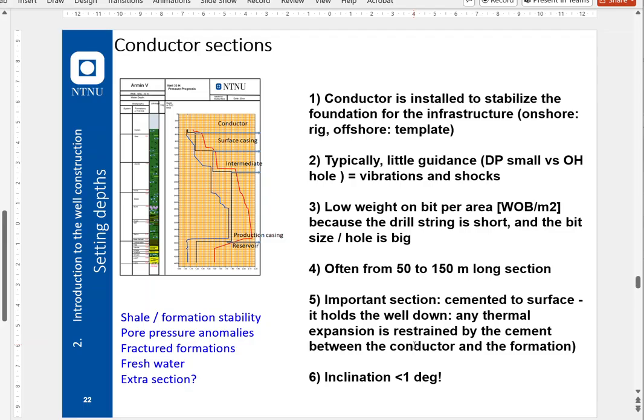What takes place is that you're drilling and you're hitting this, call it fist size or larger rocks, and it becomes like a huge shock to the bit. And one thing is the impact into the drill string. And another would be that it kind of deviates because you're hitting a physical restraint in your path of drilling. So that would make a deviation,